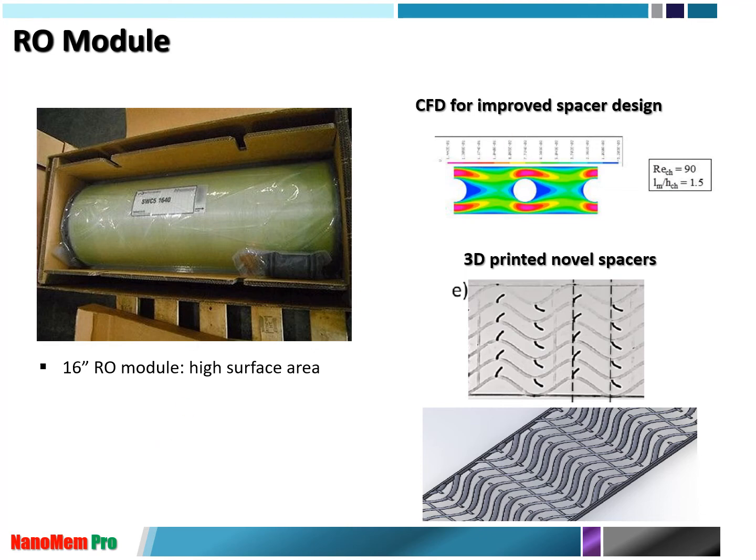And also people nowadays develop spacers using 3D printing, and they try to minimize the overall biofouling and membrane fouling on top of the RO membrane. So that's the RO module. Also, people look at bigger sizes, because a bigger module and pressure vessel can improve the overall energy saving performance.